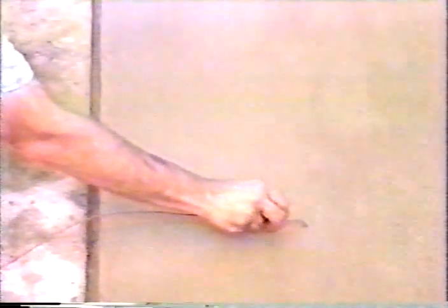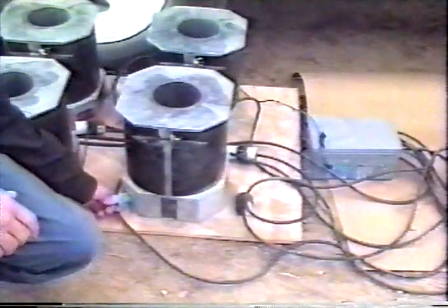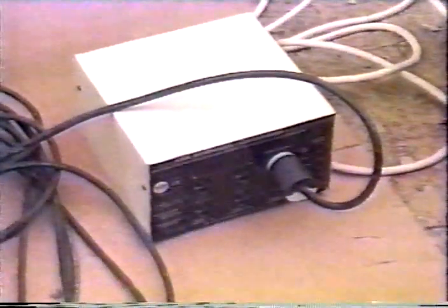TMC equipment includes 6 4x8-inch insulated cylinder molds, a heat controller with 6 cables to connect to the molds, a thermocouple wire that extends from the in-place concrete to the controller, a connecting wire between the controller and one mold, a power supply, for example, a 1,000-watt generator, a voltage regulator or stabilizer to prevent any equipment damage from voltage changes, plastic covers for the molds, and finally, form-releasing oil, such as WD-40.